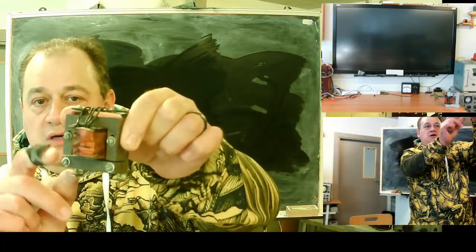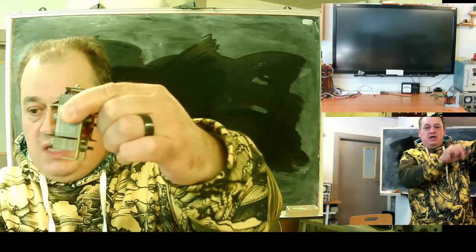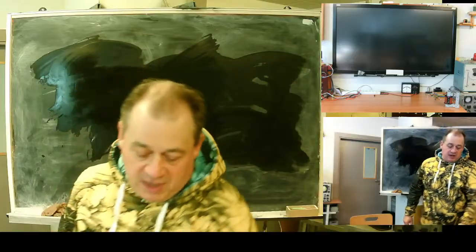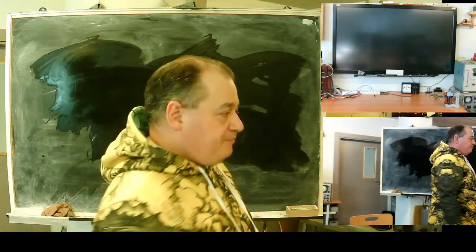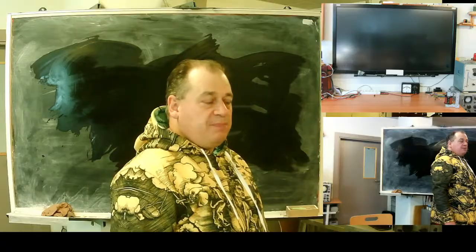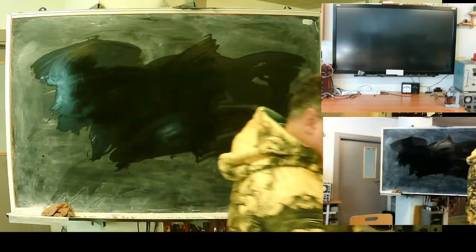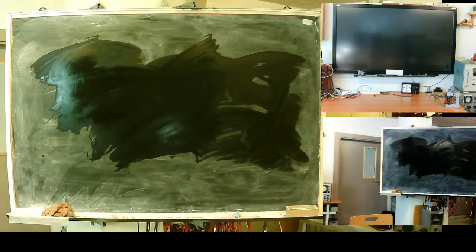This one is adjustable. See, the air gap in the magnetic system. An air gap in the magnetic circuit decreases load capability and increases linearity. It's done for the sake of linearity.